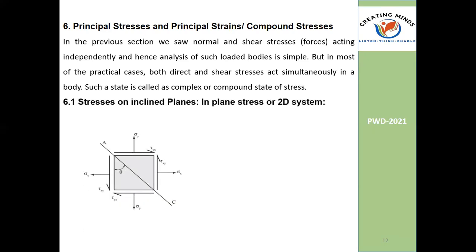So this is the thing I have explained. Sigma x in the x-axis direction, sigma y in the y-axis, tau is the shear. See, don't be confused, because the tau values you have here, these two are always equal. You are not getting two different values. But you just see the thing, sigma x is different. These x values are the same. These y values are the same. These are pairs. These are two pairs.